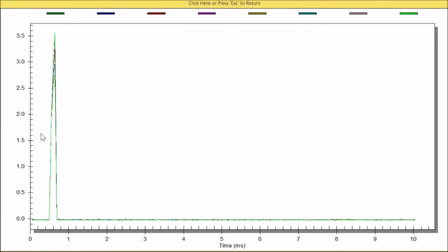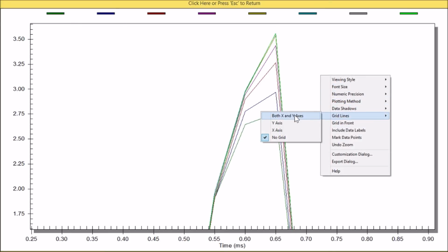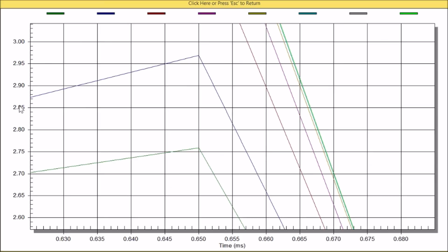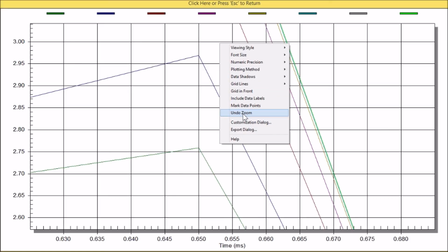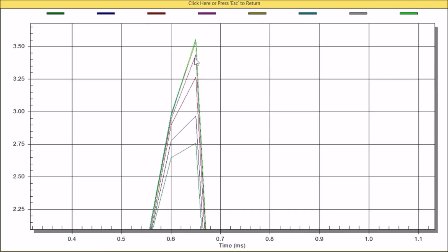Maximize. Measure our path, grid line, y-axis, 1, 2. If we look at this, 2.8 volts is right here. And so we had a count of 2. 1, 2, 3, 4, 5, 6. So we could also use 7 as a count if we wanted to. 3.1, 3.2 volts is our reference. We had a count of 2. We know the maximum count for the 2.8 volt threshold was 6. So we had stored 4 pulses in the capacitor when it was out of the EDU circuit.